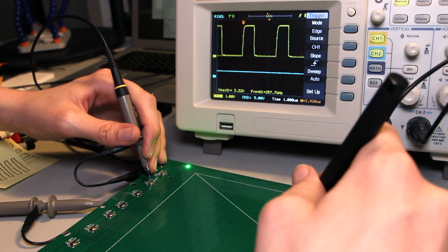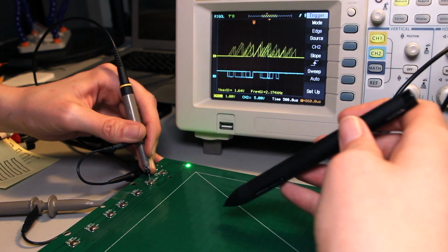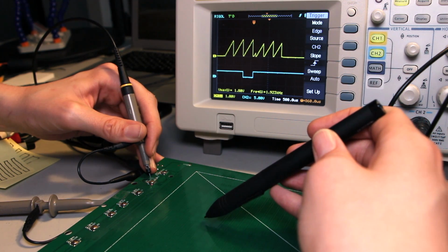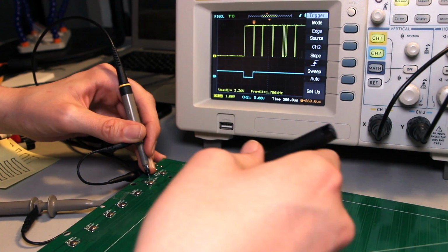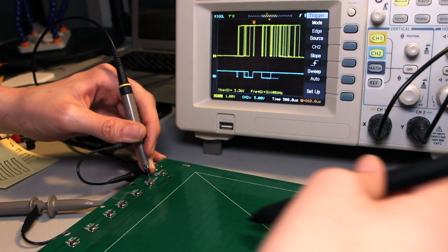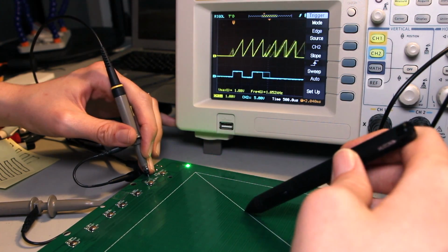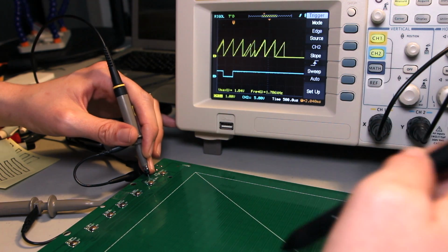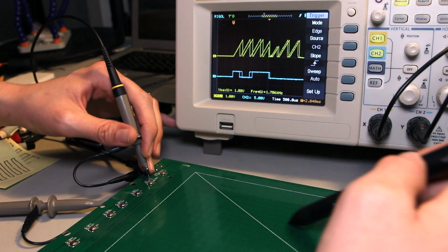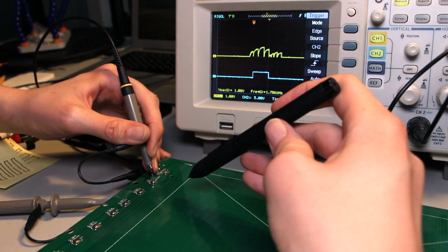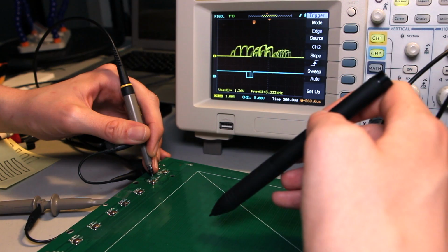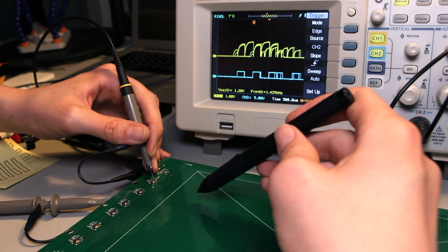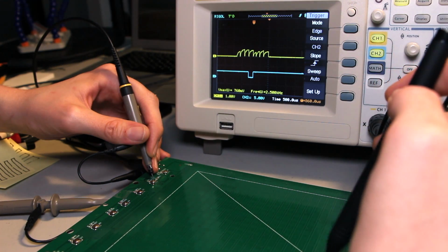what we would expect. This signal looks like the result of an analog integrator measuring the signal strength of the received signal at all the sampled coils. This signal seems to be the gate that turns on the integrator. It looks like when the tablet already has a lock on the pen's position, it only has to look at 4 sensors in the x-axis and 4 sensors for the y-axis. By comparing the signal strength received on each of the scanned coils, the tablet can estimate the position of the pen fairly accurately.